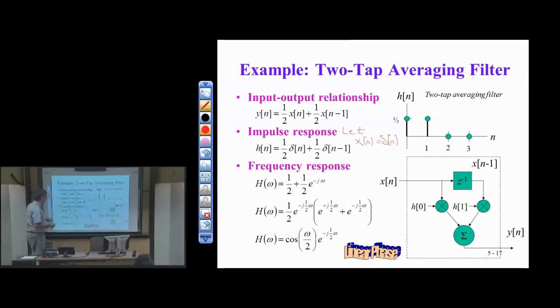So the Z transform here, which you did on homework 1, is true for Z not equal to 0, just to avoid the division by 0 case. And now I can substitute for Z e to the j omega to get the frequency response. This is just the frequency response where I've substituted Z equals e to the j omega.